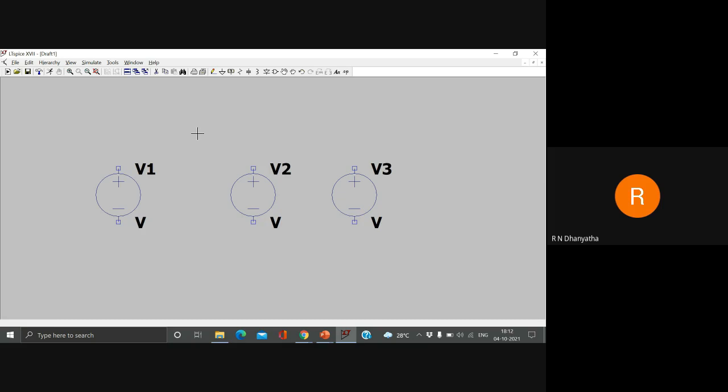So what I'll do is, I have a symbol known as scissors here. I'll just click on it, and bring it towards the component which I want to be deleted. I'll just click on it, and it goes away. Click, and it goes away. So in this manner, if you want any of your components or any of your extra wires to be cut, you can use the scissor symbol here. And again, in order to get out of this, you need to click escape.